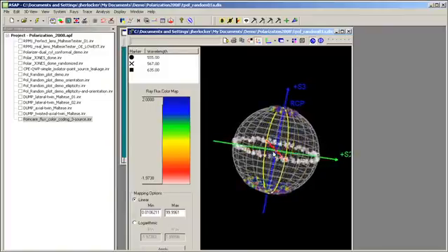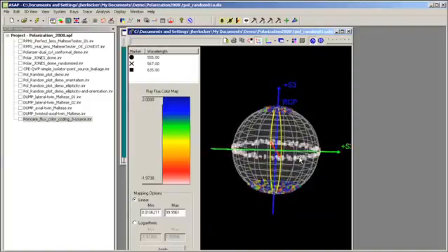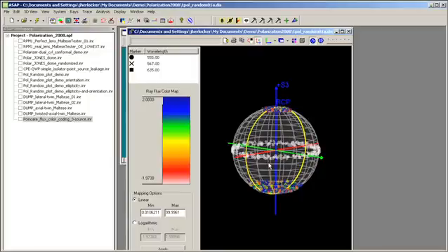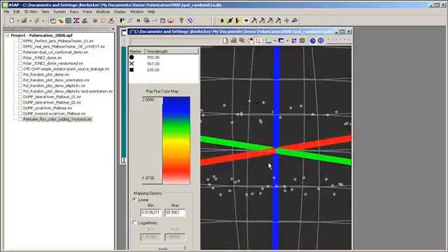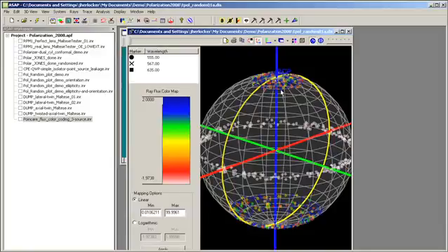In the Poincare sphere that we see here, we have right circular polarization at the top, left circular at the bottom. The equator represents linear states with different orientations, and each point, therefore, represents the polarization state of one ray. The color of each point represents the flux of that ray. So you see that we have, for instance, these blue rays have fluxes that are approaching 2.